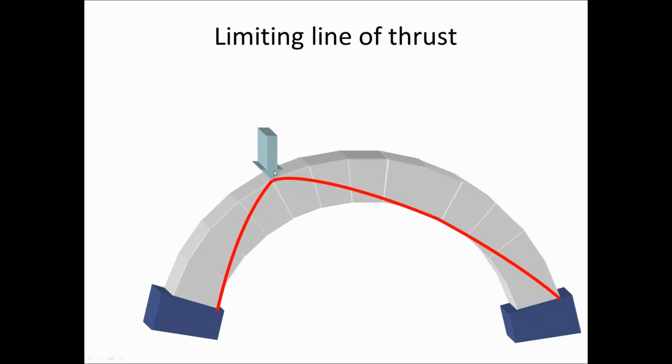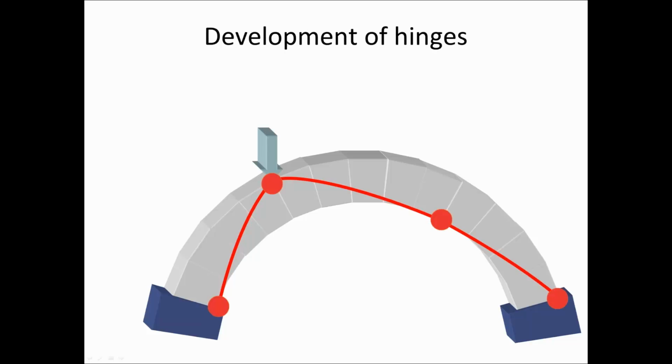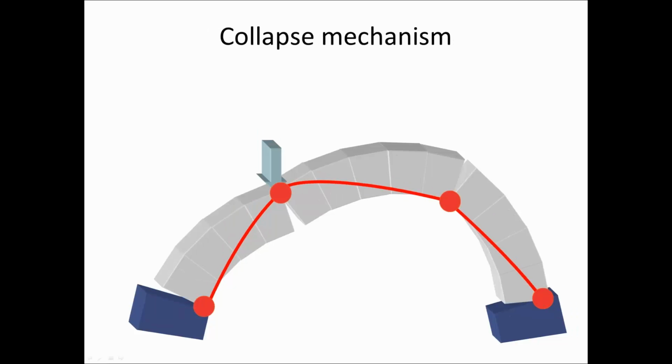And one possible extremity is when you have a large, in this case, eccentric load on the structure, such that you transform the masonry arch into a mechanism. At that point, the line of thrust is uniquely determined, and we can also work out very easily what the maximum load is, or what the load required to cause that behavior is as well.